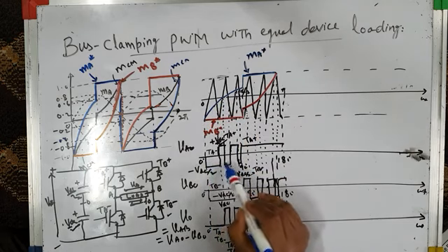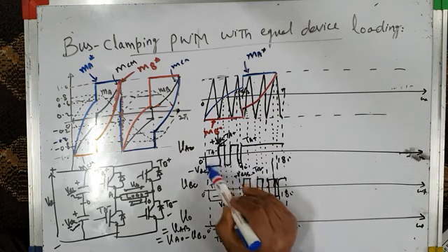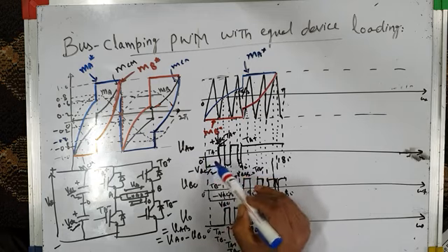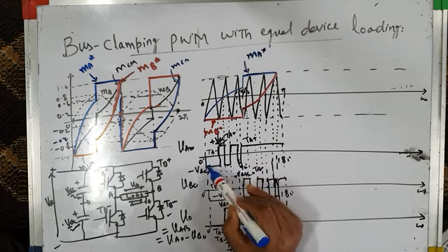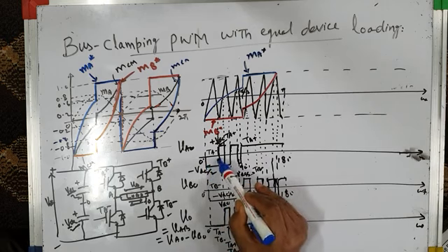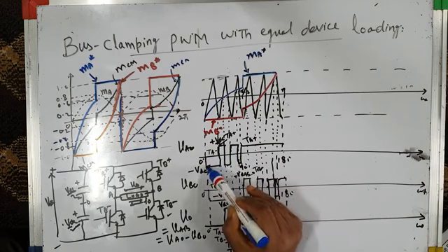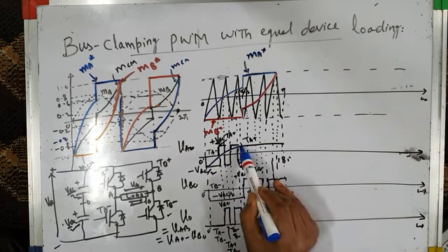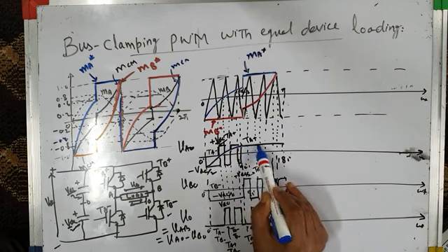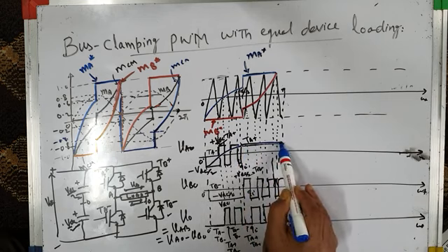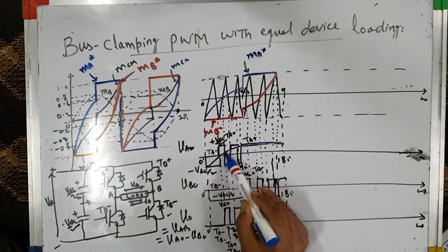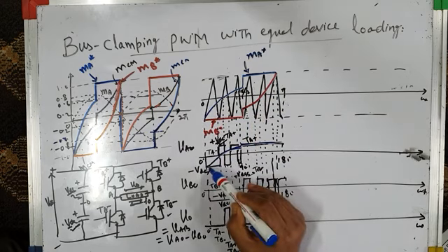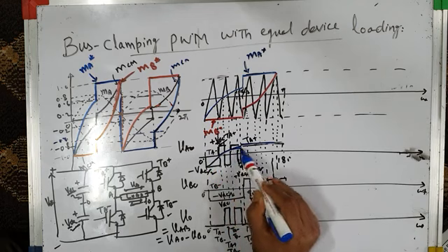So if you take the average value of voltage pulses in every carrier cycle, the average value will be like this. You can see it. It will increase somewhat like this. During this carrier period, average value is negative. Then as you move ahead, it will become positive and it will vary in a sinusoidal manner like this. And after that you can see TA plus is on, your pole voltage is plus VDC by 2 all through. So its nature matches completely with this. MA star is like this. Your instantaneous average value of pole voltage VAO also varies in this way.